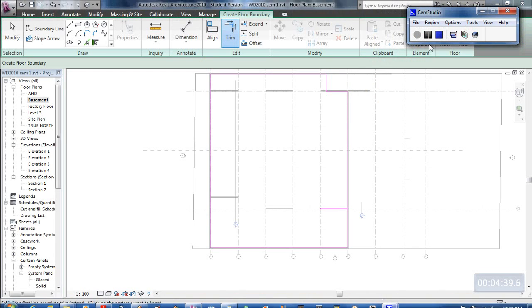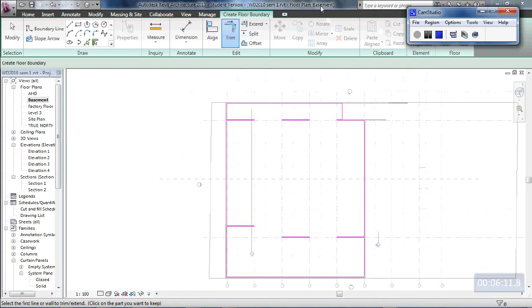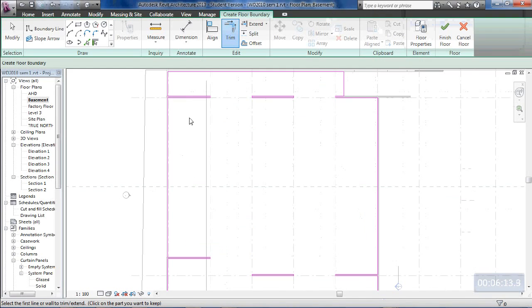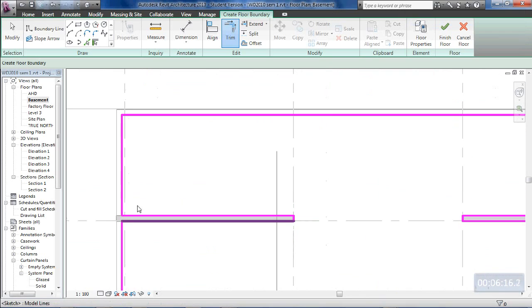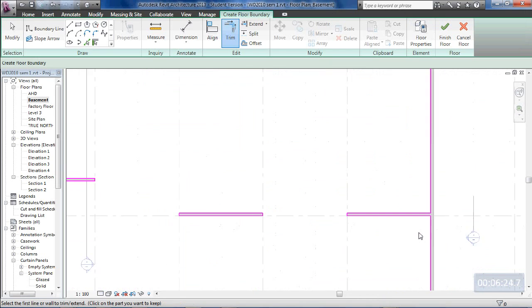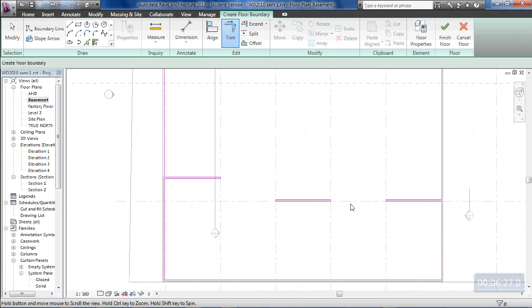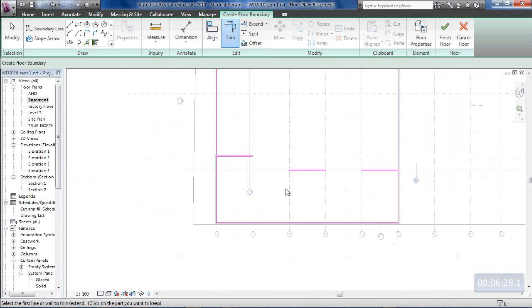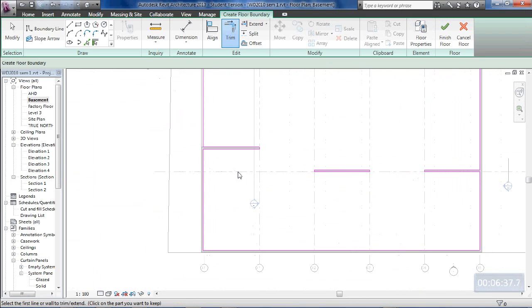Okay, so the finished effect of me tracing around the shapes would look like this. My slab does not go underneath any of the walls. I've trimmed out underneath the walls there, trimmed this out into that shape, trimmed these out like that, cut the holes in the centre, etc. I'll notice I'm actually missing another wall through here, so while I'm in this wall command I could fix that up, even though the wall is there. I mustn't have drawn that wall in by mask just yet.